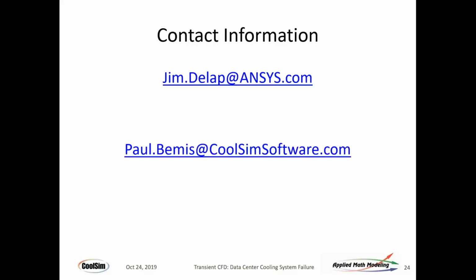However, most of us do agree in general that when you get up around 77, 78, 80 degrees, these servers will start to ramp up in fan speeds. And when they ramp up in fan speeds, the energy consumption goes up according to a cubic relationship, a fan law problem. Furthermore, the amount of air required goes up with it.